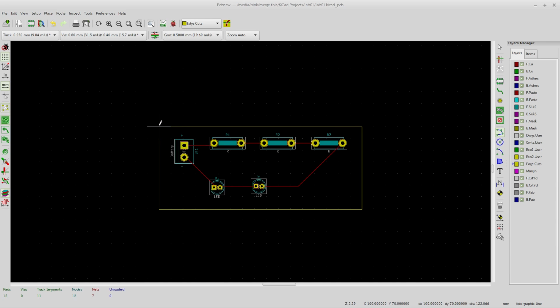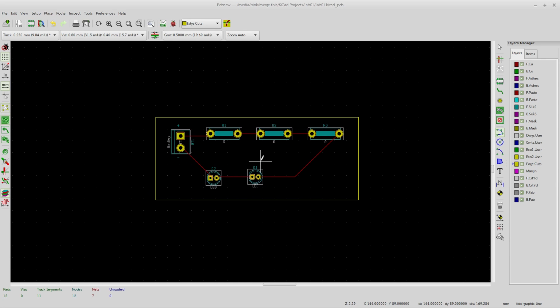Now, if you were to go to, say, Oshpark is a pretty good site. They'll take your KiCad. Last time I was there, it's been a little bit. Sorry, Oshpark, but it's been a little bit since I've been to Oshpark. But you could upload just your straight Eagle PCB or your KiCad PCB. Just straight files straight up into there. Everybody else wants Gerber files, including drill files. And so that's what I want to go off of, because that's going to be kind of the norm for most of the places in the world.